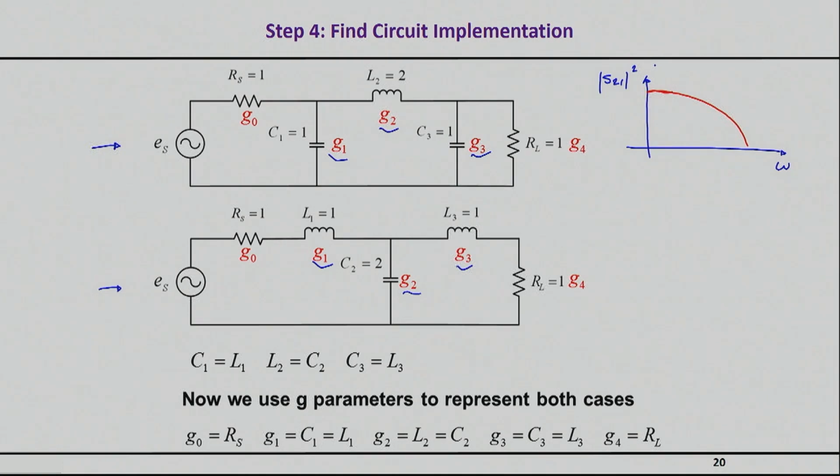But the question is, in my stop band, from here on, the filter is rejecting, but is it rejecting as a short circuit or as an open circuit? In other words, what is the phase of the reflection coefficient that you will see right here? When the signal doesn't go through, this is a reactive network. It's not being consumed in the filter. We will see cases where this signal is actually being consumed. But right now, all the signal is reflected.